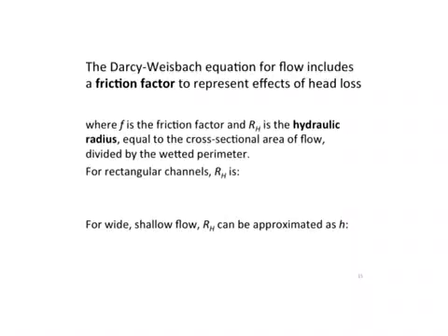So what they're assuming here is that the friction slope, which remember we defined earlier as the head loss over a length of interest, should be proportional to a friction factor, so how much friction a given unit area of stream bed has. It should also be proportional to velocity squared, and this just comes from the fact that there is usually a squared relationship between drag or total friction and velocity. And they'll just divide this by 2g.